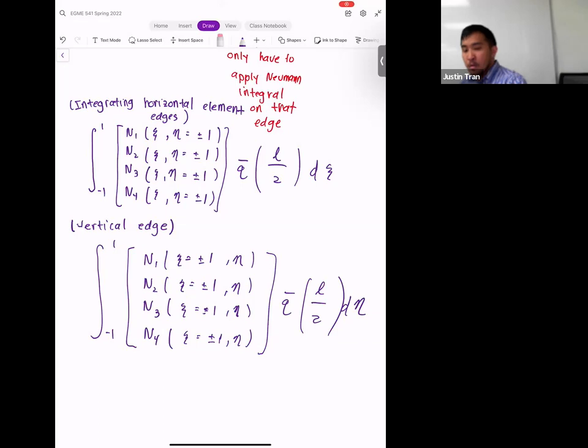For the exam problem on the non-reference element, can we expect to have more elements than this? Would you want us to discretize it over 2 elements? Like in the book, it's 4 elements, I think. The most I'll ask you is 3. But you could take some shortcuts here. Use the fact that I'm going to ask you with linear shape functions. I'm not going to ask you quadratic. When you take the derivatives, you end up with 1 over the length, minus 1 over the length, and it all ends up out front because it's a constant. So you take advantage of that to speed up your calculation.